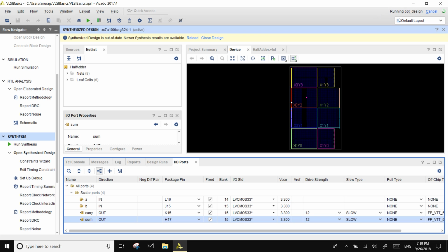So what it's doing is a place and route between various LUTs, muxes, and flip-flops using the buses inside this FPGA and switching matrix. It is optimizing the design, which means that it is placing them in a smaller section closer to the IO pins. So once this is done, I'll show you what this is.